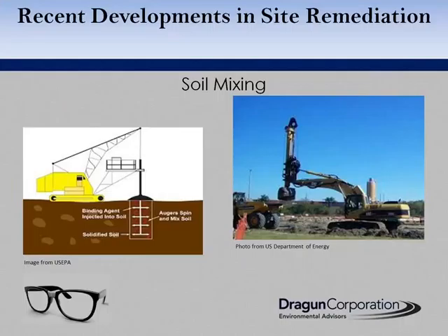Some of the advantages of using the augers is that they can typically go a lot deeper than a traditional excavator without having shoring or benching to get down there, or sloped sidewalls. You don't need sloping or shoring.